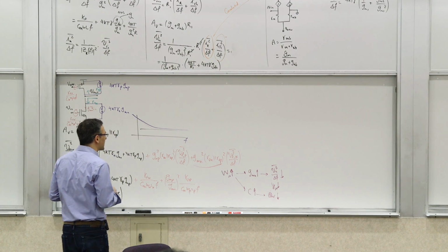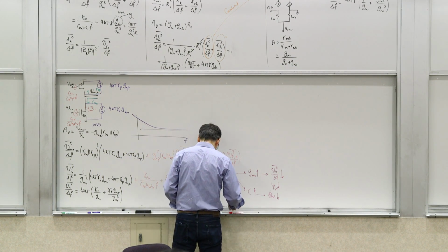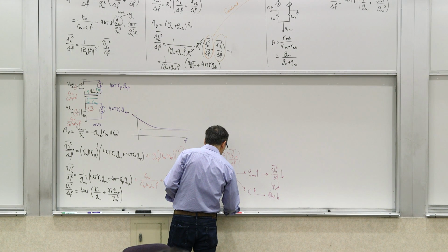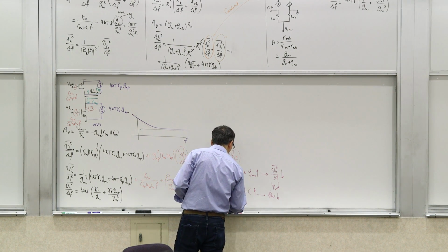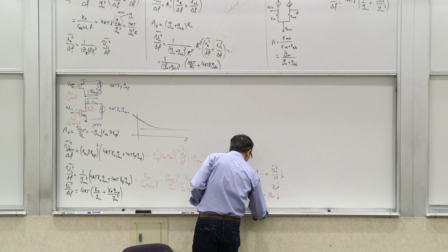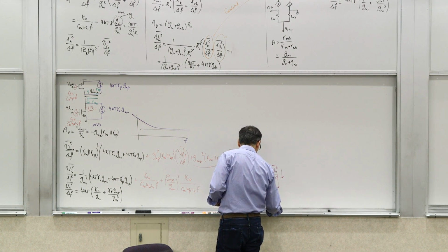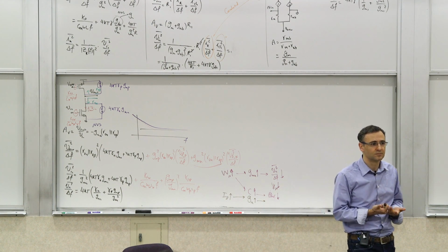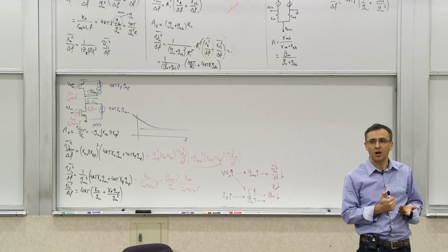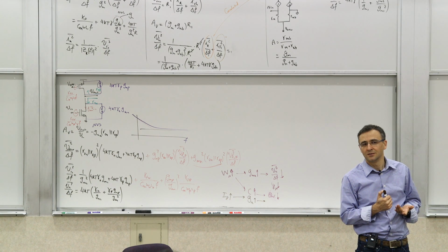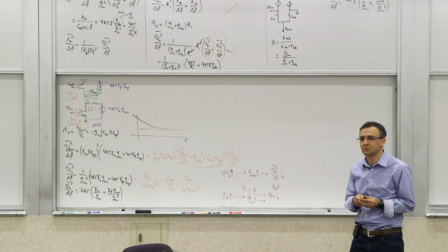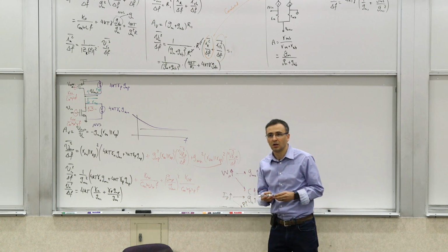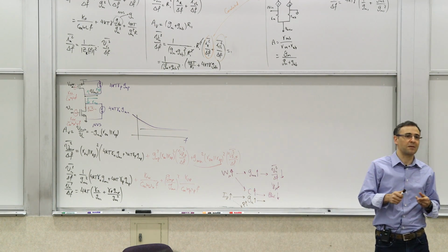Now, how about the current? What if we scale the current? Let's say we take the I bias, ID, and increase it. What would happen? Well, GM goes up, which would again help with the noise stuff. But what is the price? It's an even more obvious price, right? It's power consumption. So the power consumption is going up too. So there's also a trade-off between noise and power.